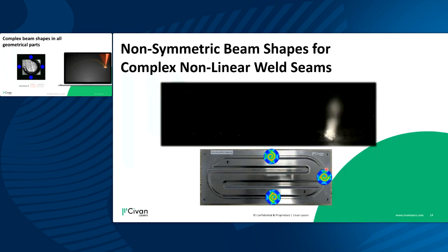What is moving the beam shape, doing the large motion movement, is a galvo scanner. But within the melt pool, in the area of a couple of 100 microns, what changes the orientation of the beam shape is the phase control, in other words the technology in our laser. This opens a new opportunity for beam shapes that were not possible with other lasers, because even if you can generate a beam shape but cannot change its orientation, the process changes every time you change the orientation. With this laser, you can maintain the same orientation in all the different parts of the weld.